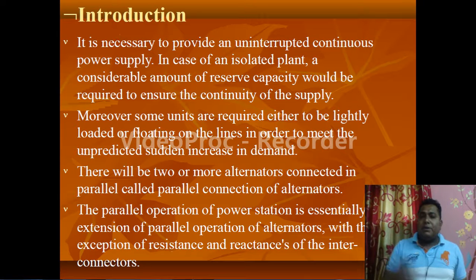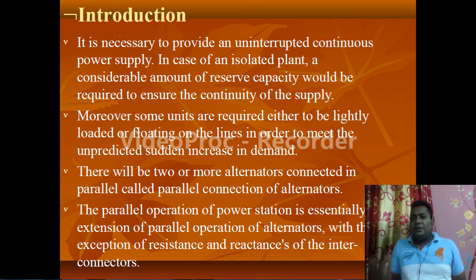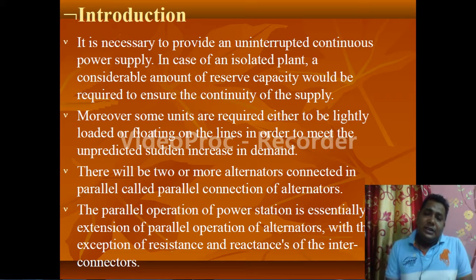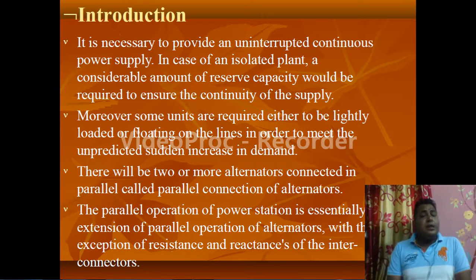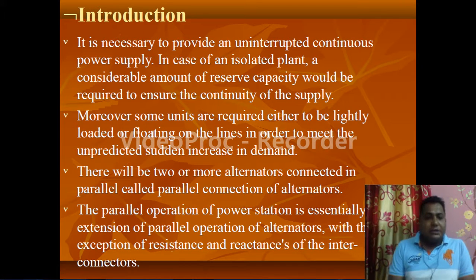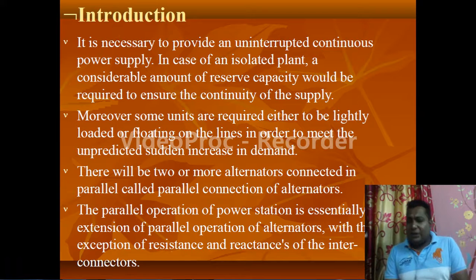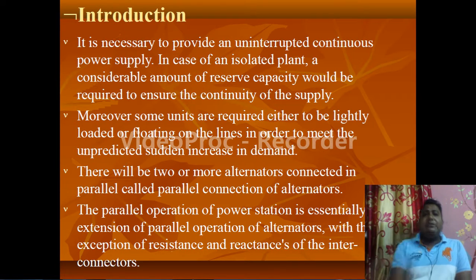If there is a problem with one, the other one is there. This concept is considered here. Moreover, some units are required either lightly loaded or floating on the lines in order to meet an unpredicted sudden increase in demand. Already I have discussed that. So there will be two or more alternators connected in parallel, called parallel connection of alternators. That is what we are discussing.